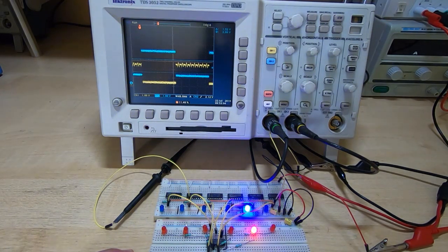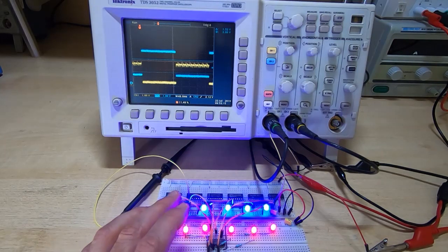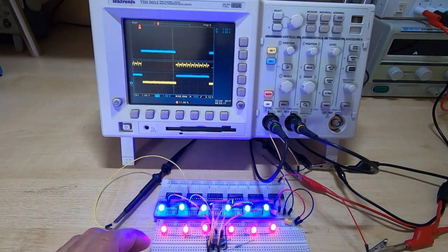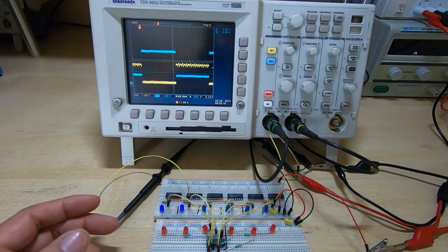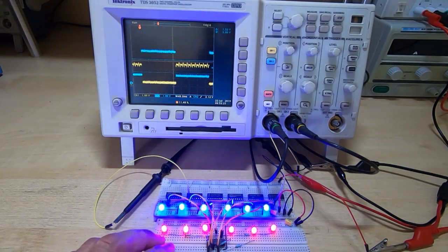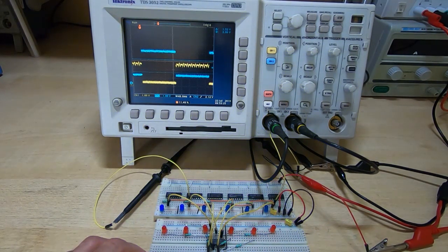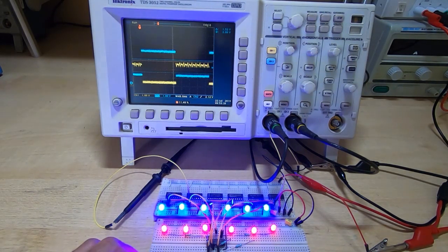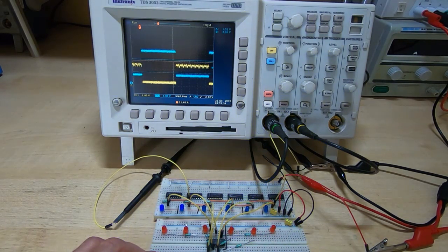All sorts of strange behavior can start coming into play because of the way the different devices behave differently in the different conditions. So you'll have an HCT which either works or will completely stop working, or you get 74 series that will sort of incrementally start reducing their output up to the point where the devices they're feeding will start to misbehave. And it can be very difficult trying to pin down exactly where the actual problem lies.